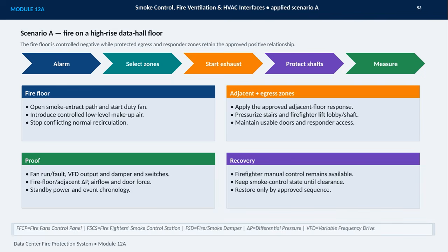During recovery, firefighter manual control remains available. The smoke control state stays active until clearance, and restoration follows only the approved sequence. These checks connect system operation with safe, documented performance.